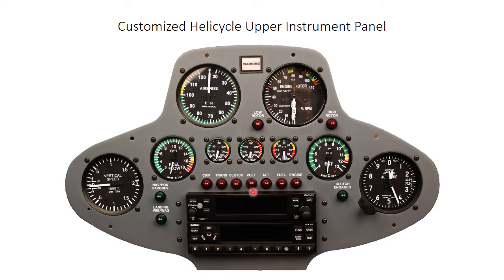The indicator lights are these dial light military stovepipe incandescent lights that I use. They take a T 1 3/4 flange light, which is an 80 milliamp 14 volt light. Comes out to about 1 watt.